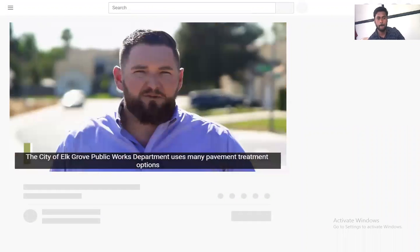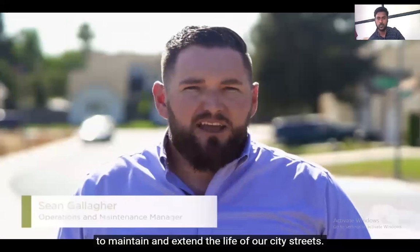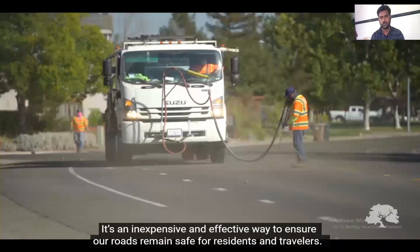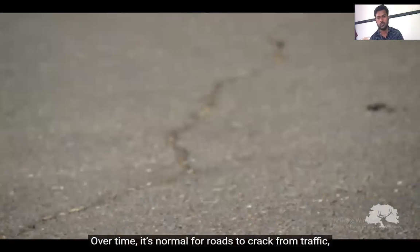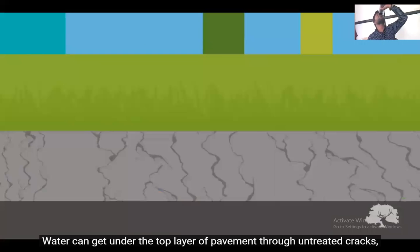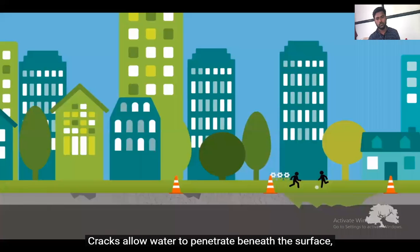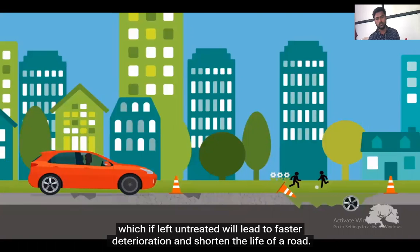The City of Elk Grove Public Works Department uses many pavement treatment options to maintain and extend the life of our city streets. Crack sealing is one of many pavement treatment methods. It's an inexpensive and effective way to ensure our roads remain safe for residents and travelers. Over time, it's normal for roads to crack from traffic, temperature changes, and most critically, water. Water can get under the top layer of pavement through untreated cracks, causing potholes, base failures, and other conditions that lead to costly repairs. Cracks allow water to penetrate beneath the surface, which if left untreated will lead to faster deterioration and shorten the life of the road.